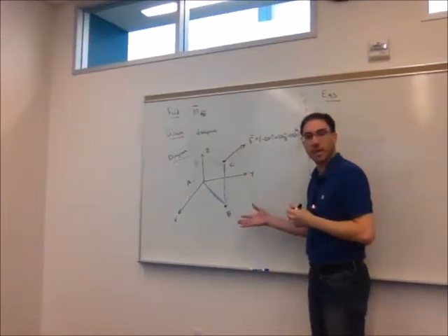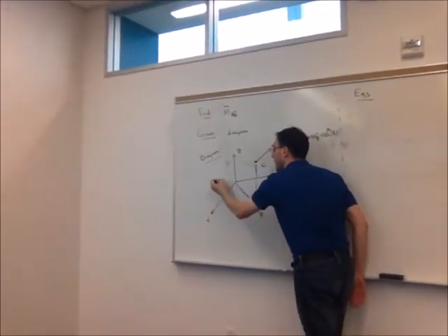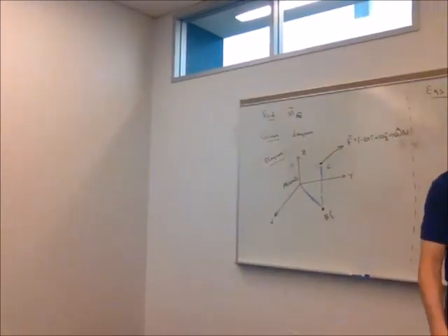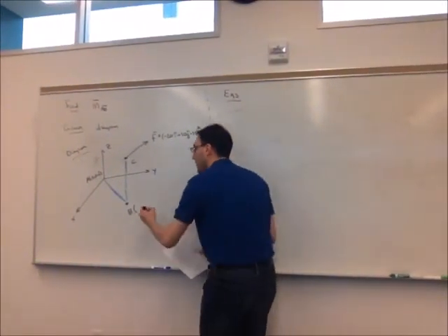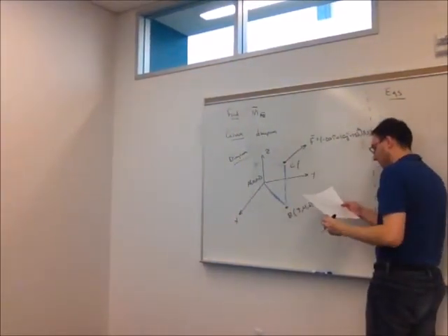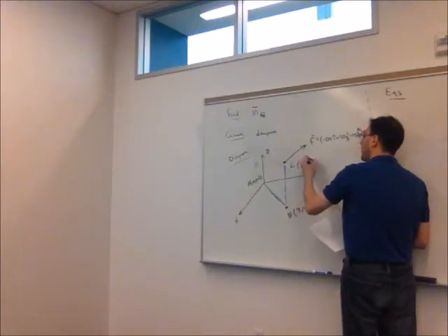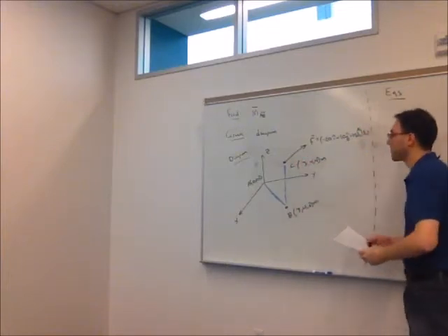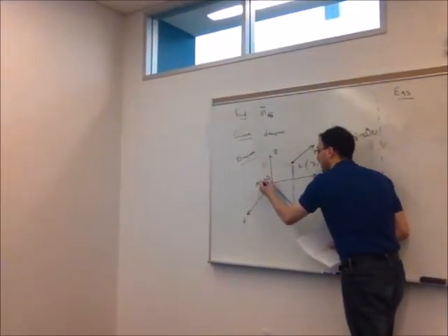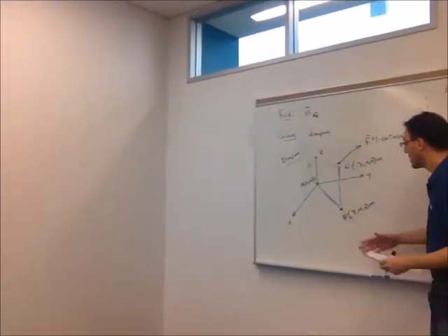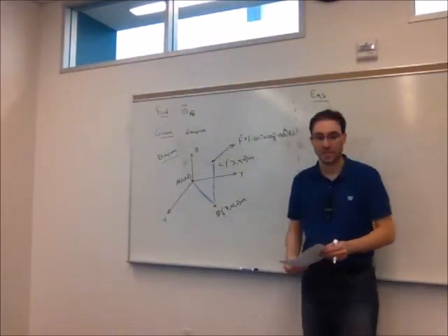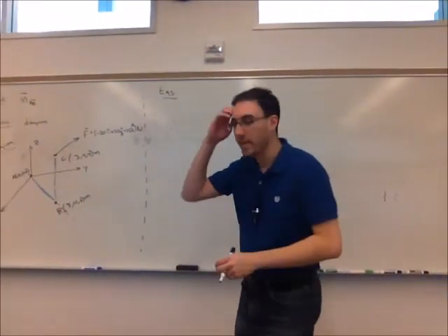And then it's 3D, so again, we want to put the coordinates of all of our points down. A is the origin. B is going to be situated at 3, 4, 0. And C is going to be situated at 3, 4, 4. So one force, again, we are interested in the moment around the axis determined from A to B. So this axis here is what we're ultimately concerned with, the moment about that. So this is the diagram we need.